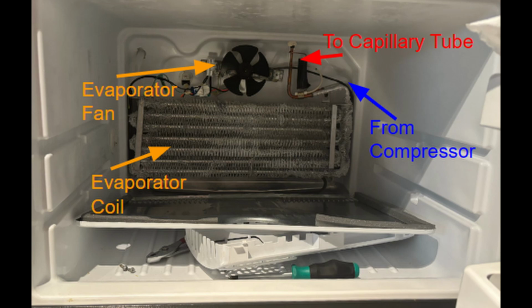Then I opened up the inside of the freezer to look at the evaporator coil. I needed to do this so I could take temperature measurements on the tubes going in and out of the evaporator coil. You can also see the evaporator fan in this picture.